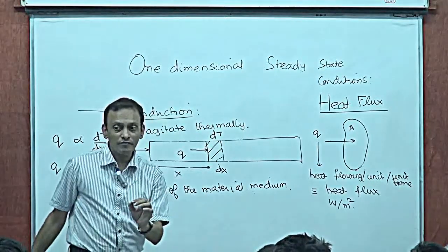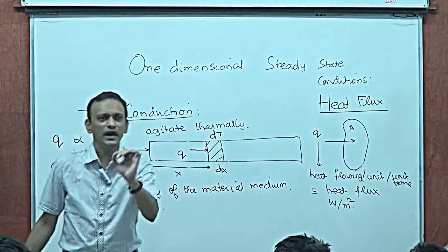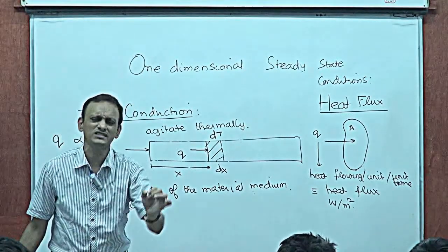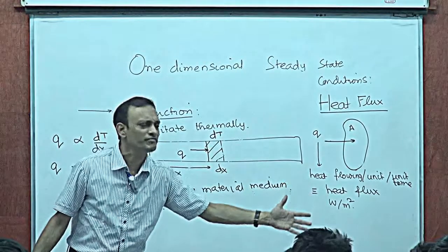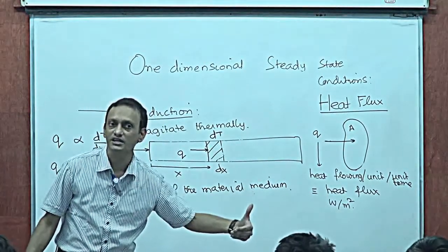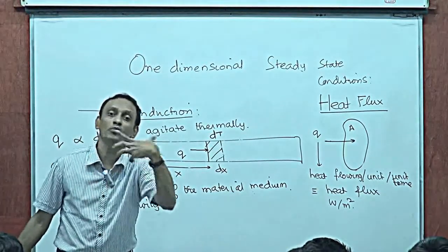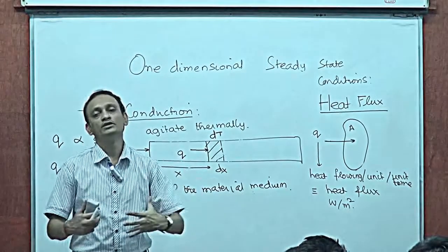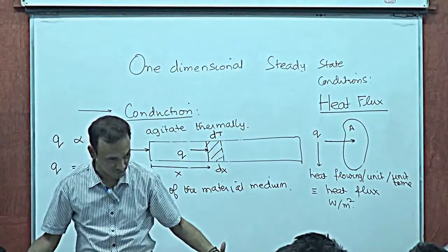For regular applications, the error obtained by taking K to be temperature independent would be so small that it's not going to affect the application. But in space applications and more sophisticated applications, we would have to model K as a function of temperature and other related factors and deal with a more sophisticated heat transfer problem.